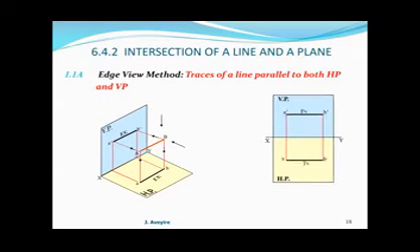Now, if we were to align the views we have on both planes such that we can see them all at the same time, that means the horizontal line is rotated downwards, so it's vertically aligned with the VP plane. Then we have the figure shown on the right side, where we have the front view FV, the top view, and our lines of projection or correlation shown by vertical lines showing the correspondence.